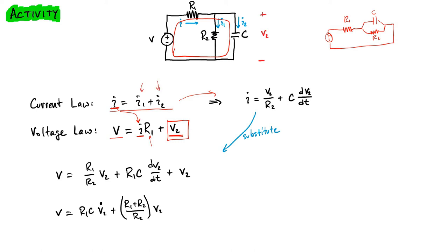I1 is the current across the second resistor, so we can just replace it using V equals IR, and that gives us the V2 that we need. In the case of I2, this current is the current across the capacitor, so its circuit element relationship gives us the derivative of V2. Again, that gives us V2, what we need to know. Now we can substitute that in this position for I, and that will finally get rid of all of the other variables and leave us with an equation that is entirely in terms of V2. So all of our terms are V2. This one came here, and this term expanded into both of these terms here.